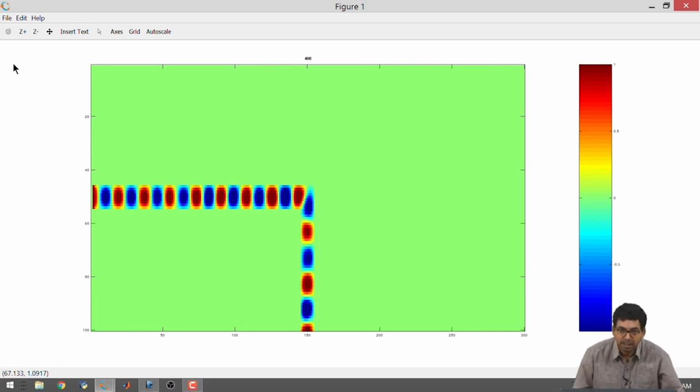You cannot conclude that it is a single mode, multi-mode and all that, because maybe multiple modes are there and you did not excite them, or the configuration is such that single mode was dominant and then it did not get converted due to several other reasons. But it is clear that the operating frequency, the size of the waveguides, the bend that you have, the size of the source, all of these are ways for us to excite and probably propagate different kinds of modes in your parallel plate waveguide. So, I think with this 90-degree thing, it should be clear that indeed you are seeing some waveguiding action.